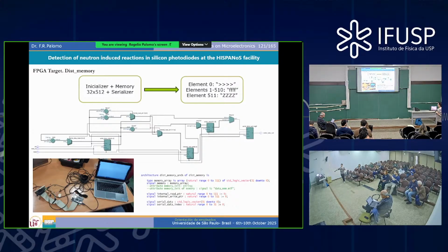You don't have to describe explicitly the memory array. Those are implicit commands in VHDL, and the compiler will interpret that you are looking for the flip-flops without the combinational electronics around.